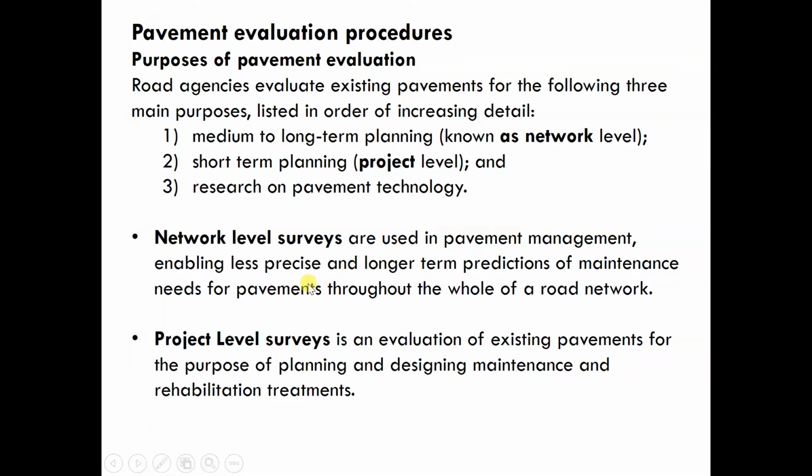The network level surveys are used in pavement management, enabling less precise and long-term predictions of maintenance needs for pavement throughout the whole of a road network. So they will need to do some survey for the whole network. For example, in Auckland, Auckland Transport will need to choose certain roads to do the survey, and they cannot afford to do the whole length of all the roads.